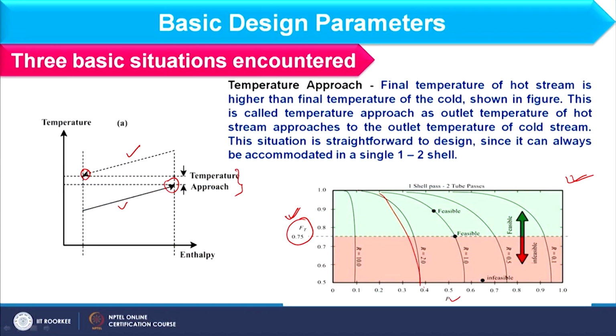Fine. So, if you consider this diagram, here I am having a hot fluid, this is the hot fluid and this is the cold fluid. So, at each point we have cold fluid lesser than the hot fluid, this much temperature difference is always there. Fine. So, this is basically the proper temperature difference, and heat transfer can occur easily, right. So, what is the point? If I consider counter current flow, at every point cold fluid temperature will be less than hot fluid temperature.